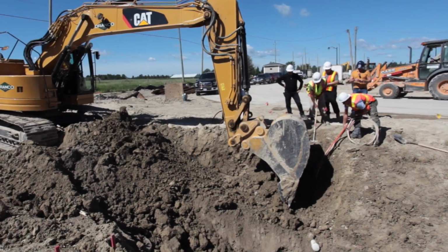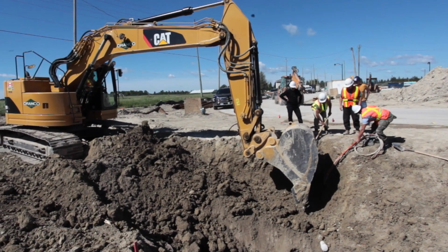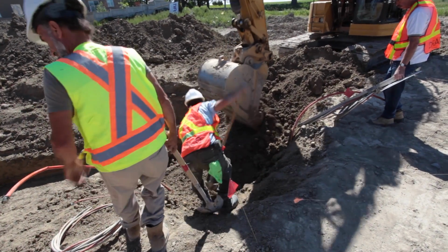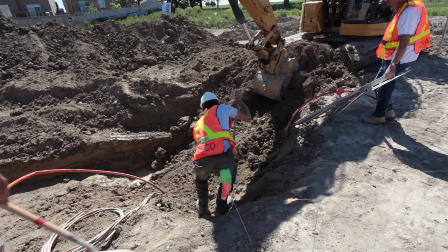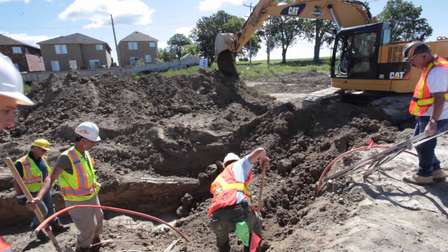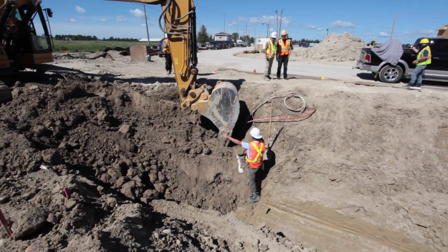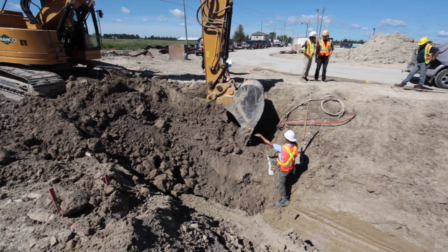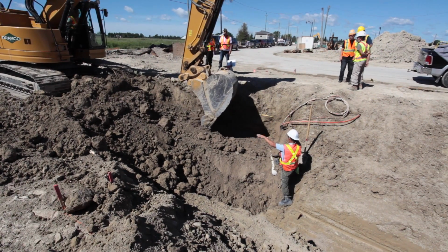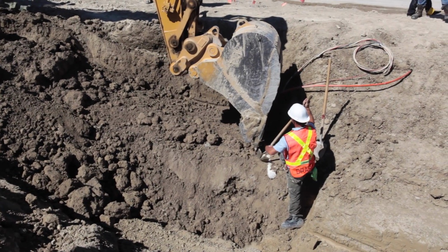Also, if unsuitable subgrade is encountered, additional trench depth should be excavated to remove the unacceptable material, then refilled and compacted with suitable material. For the purpose of this video, and to demonstrate the benefits of the sewer lateral extensions as endorsed by the OCDCA and our union Local 183, we have excavated and exposed the test fittings located at the property line. The purpose of the extension of the laterals is to create safe work environments by providing proper sloping, and also in consideration of utilities infrastructure damage prevention.